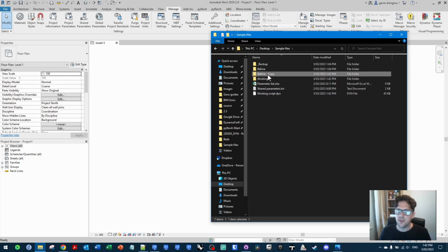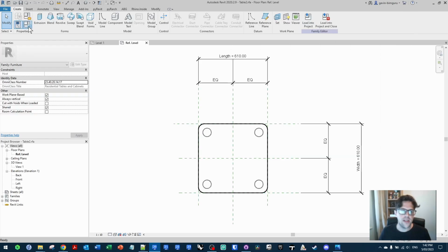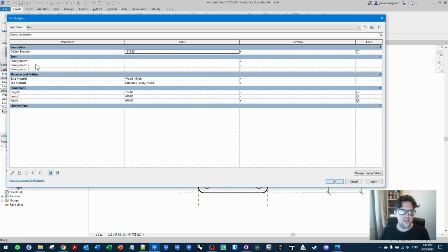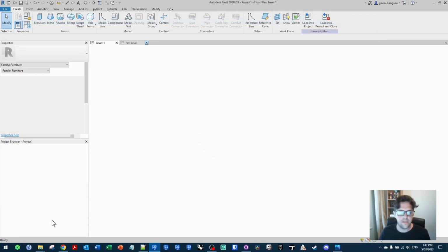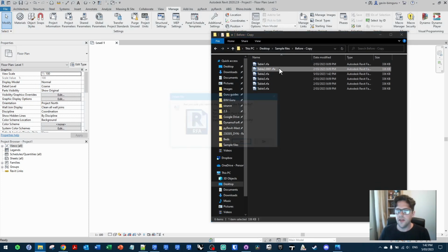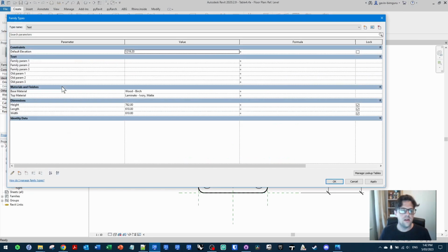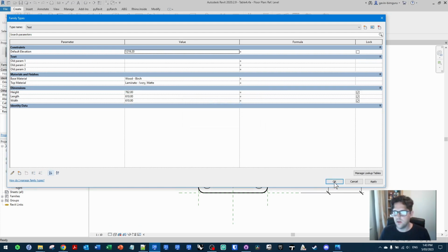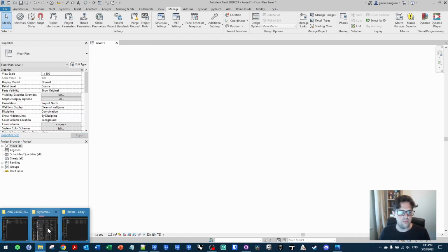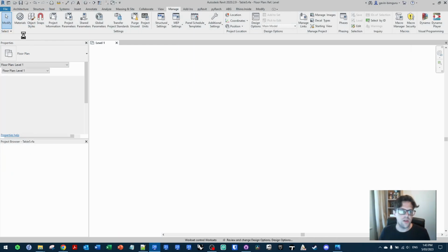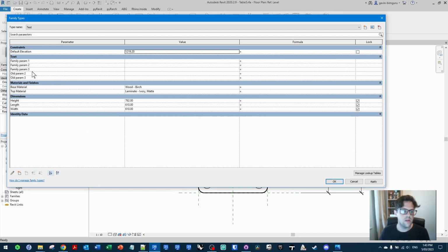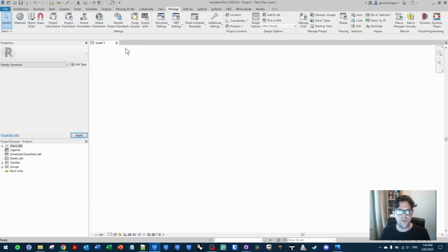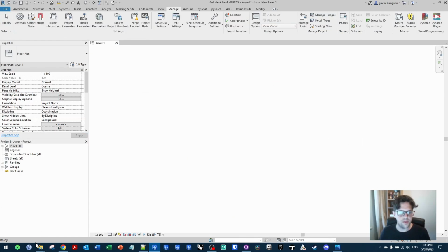And I believe if I take one of these and rerun this process, so if I take this before file, just make a copy, and let's say maybe one of them we just want to take out some parameters. I'm pretty sure they don't all have to be present for this workflow to work. So let's just leave family param 1, 2, 3 in this one. And let's also maybe leave old param 1, 2, 3 in this one. And let's leave a real mixture of parameters in table 5. Great. And I believe the script should be able to work with partial replacement.